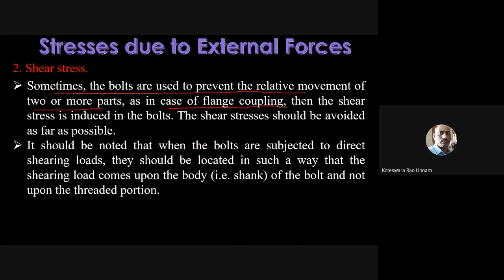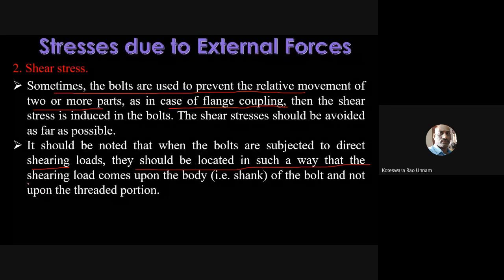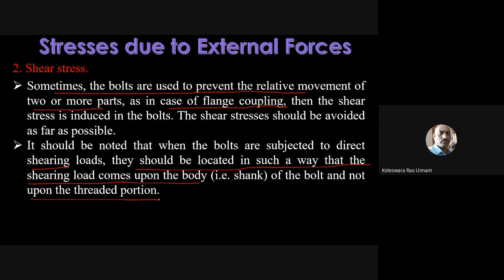It should be noted that when bolts are subjected to direct shearing load, they should be located in such a way that the shearing load comes upon the body of the bolt and not upon the threaded portion. And also, one more point we need to remember: as long as it is possible to design the joint such that there is no shear stress on the bolt, that is the better practice or good practice.